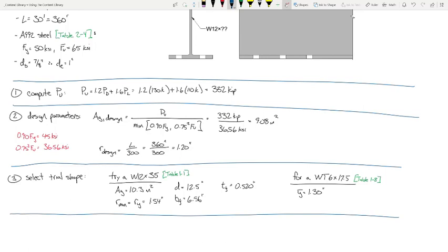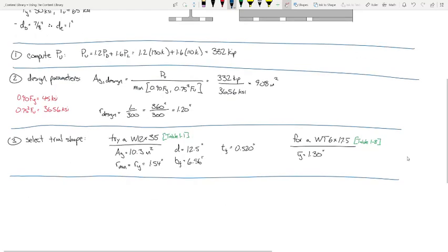Go up a shape. So we go to the W12 by 40. Is that right? Yeah. So we would try a W12 by 40, get this property for a WT6 by 20, and just do it all over again. If we do step 4 and step 5 and we have a really over-designed member or a really low efficiency, we go a step down, do it again. So it's just repetitive, okay? Now let's see what we can figure out in step 4.